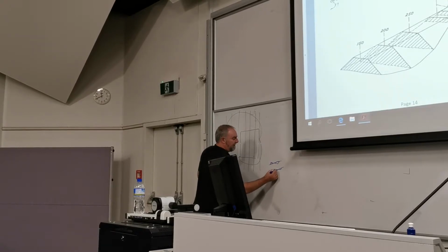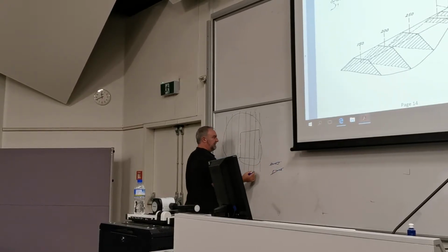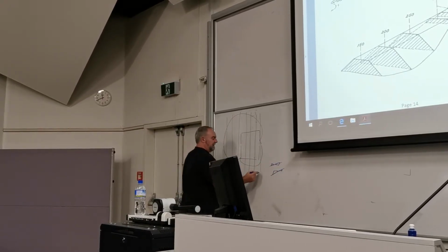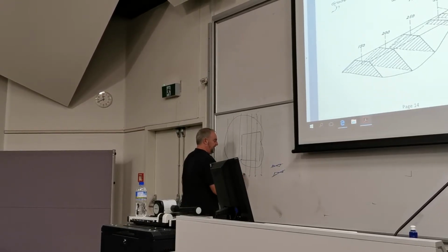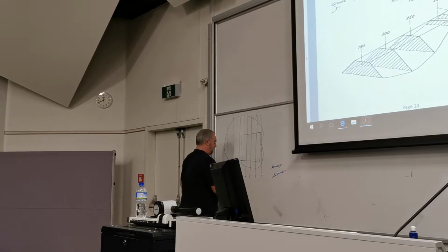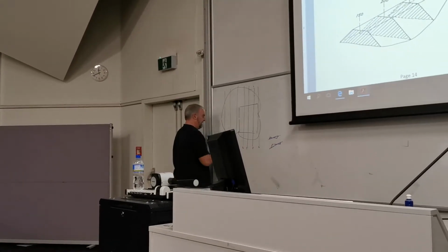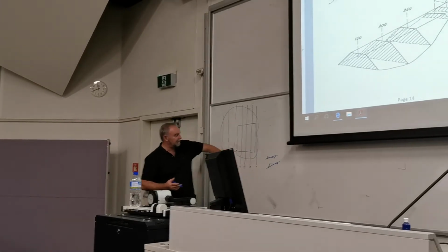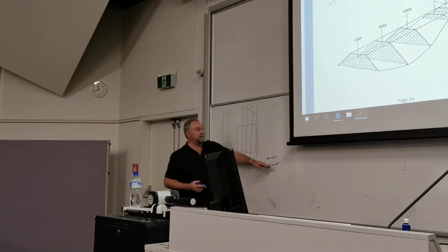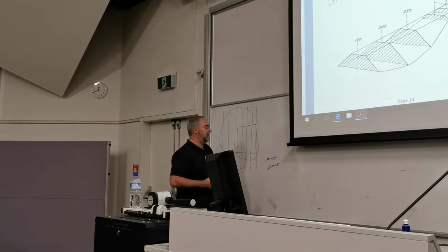And you can work out a chainage along here, starting from one end. That might be 2 meters, that might be 5, that might be 6, that might be 8, that might be 10.5, it might be 11 or something like that. So you've got a chainage as you work your way along. So it's a bit like those sections I showed you of the road.